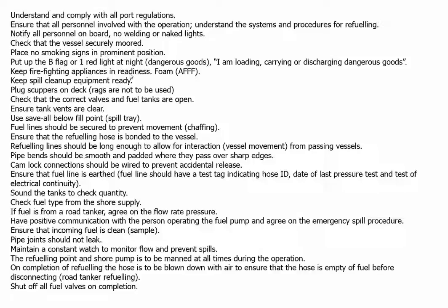Keep firefighting appliances in readiness, with a foam AFFF extinguisher and a spill kit. Plug the scuppers on decks. We'll talk a bit more about those. Ensure correct valves are open and fuel tanks are open, vents are clear. Have save-alls or a spill tray below our fill point. We'll talk about that. Fuel lines secured to prevent moving or chafing.